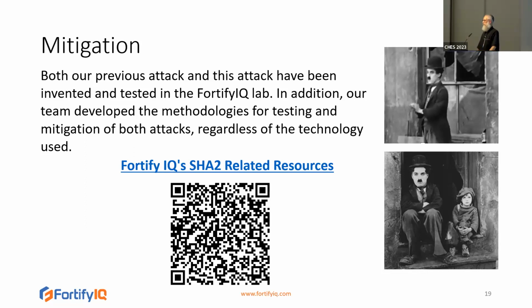Okay, so the theoretical attack is based on the assumption that this is the leakage model plus maybe normally distributed noise. Now, of course, in the physical reality, the leakage model is not so. So the proof that the attack works does not necessarily apply to the physical world. But here we have experimental results that show that in the real leakage, we still are able to find the key.